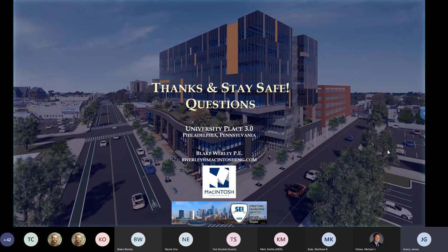Was there a permanent hoist installed above for lifting that, or the ceiling or the floor slab designed for whatever point load it would take to pick that in the future? Yeah, we did consider that, and the location made it feasible just to do with a truck crane whenever that separate mini project might be necessary in the future.